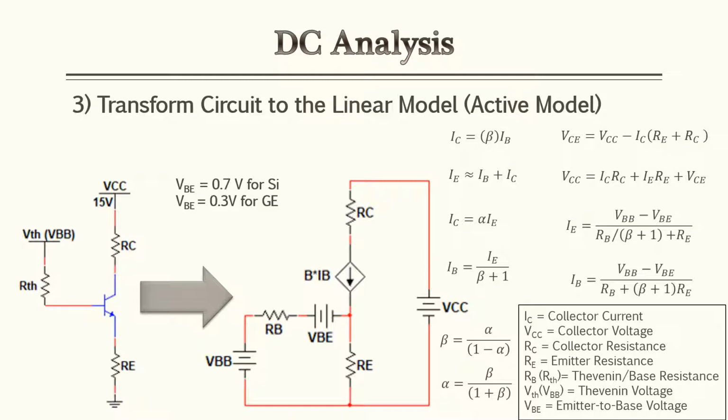And the last thing of note, be aware that I use all capital letters for all my subscripts when determining these equations, or when I'm displaying what I have on my circuits. For example, my collector current, it's a capital C for IC, and then same thing with the current for the base, current for the emitter. They're all capital letters for the subscripts. This is very important. When you do an AC analysis, they're going to be lowercase. And when you do the AC analysis, they may ask for uppercase depending on what equation you're plugging and chugging in. So be aware there are two different subscripts based on what they're asking for. Lowercase is AC, uppercase is DC. And we're only doing the DC analysis for this lesson, so be aware all of my subscripts should be capital letters.